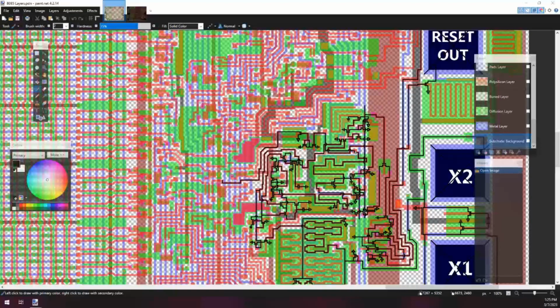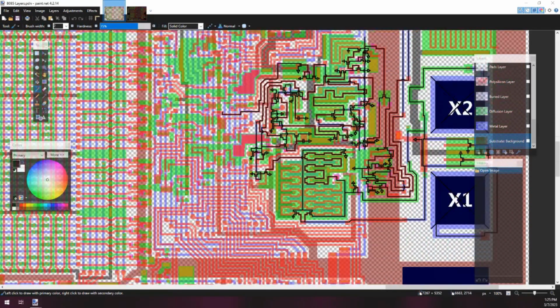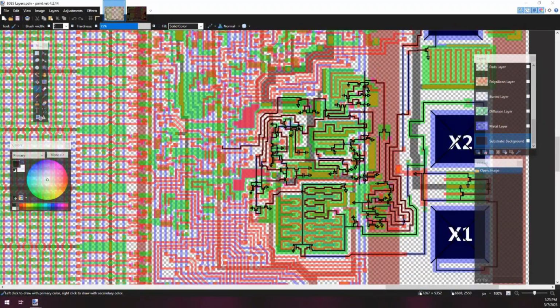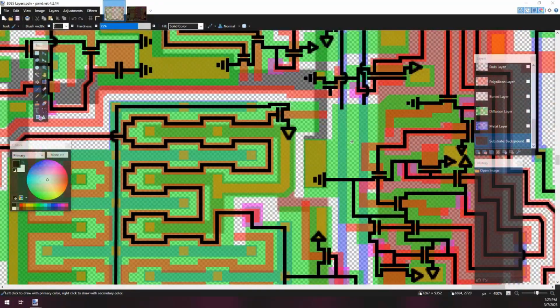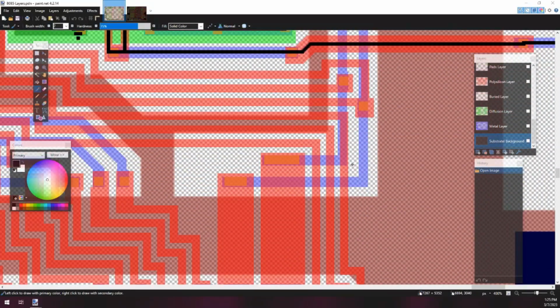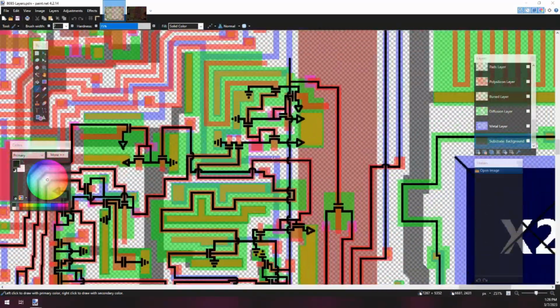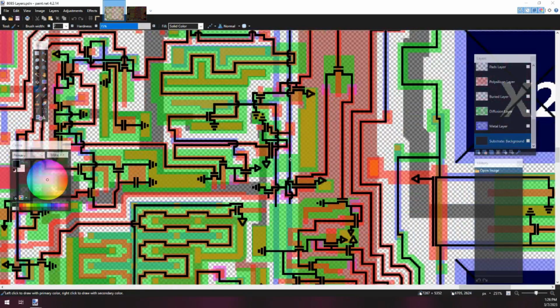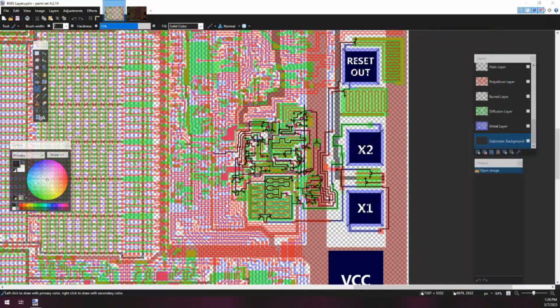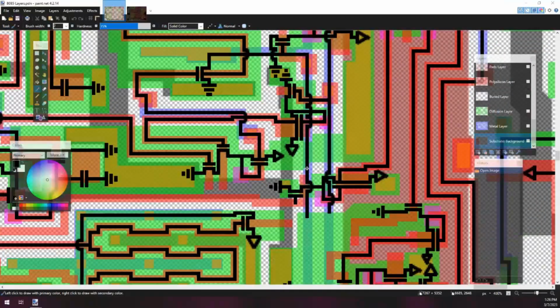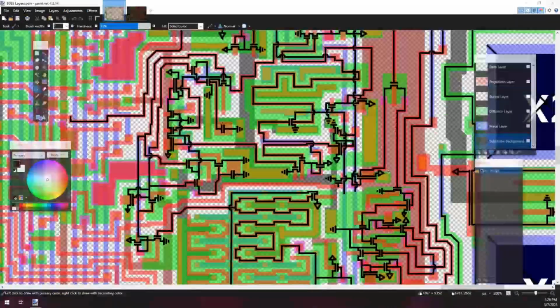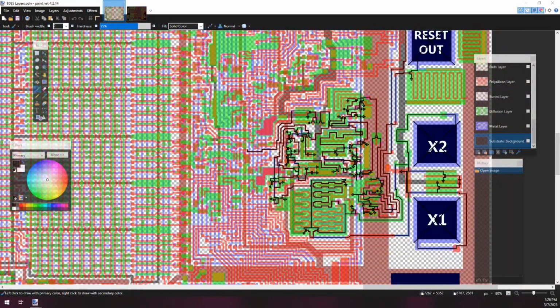What's more is there's also lines that are going throughout the chip here. For example, you can see these 2 wires right here. These actually span the entirety of the chip, because these are the clock signals, basically, phi 1 and phi 2. So that is what controls the timing. That goes all over the CPU, but you wouldn't know that at a glance. There's no visual indicator.